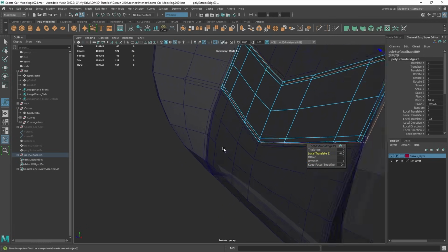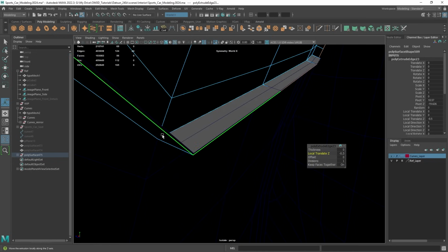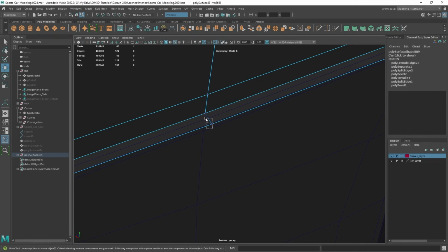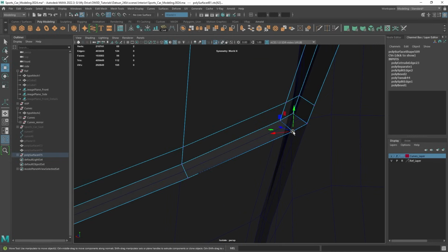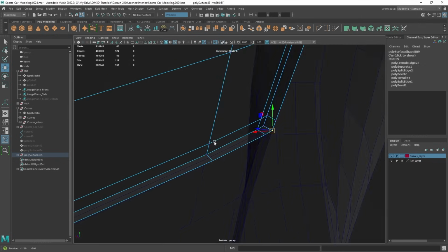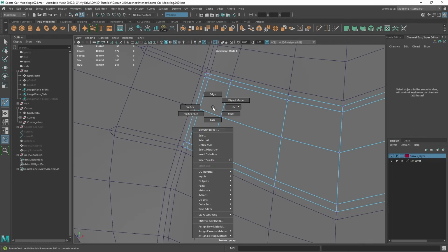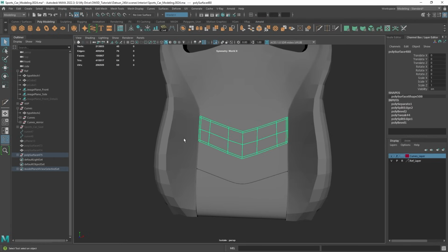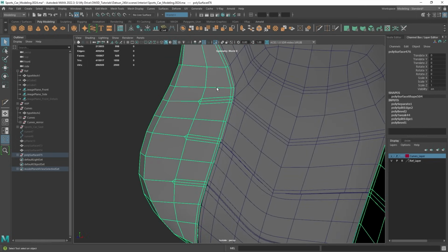Now this time, you'll notice if I get in here, sometimes it does it where they go off in 2 different directions. If that happens, then just simply go into vertex mode and I'll snap them before I add the division. And so snapping these here, holding V, left click, and there you go. So we're just snapping vertices here, and hold Shift right click, multi-cut, and then there you go. You're just now getting these nice panels in here, and I use that process throughout the rest of the model. Now you notice I over beveled here, and that's no problem.